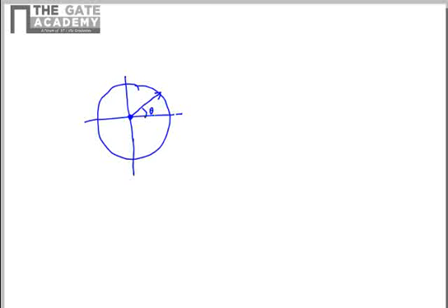The harmonic motion notation by using a vector rotating about the center also helps to define a simple equation for the vibration model. So we have considered that a vector in space having theta degrees from the x-axis is rotating with an angular velocity of omega. When the projection is taken along the y-axis, you get a sine wave.